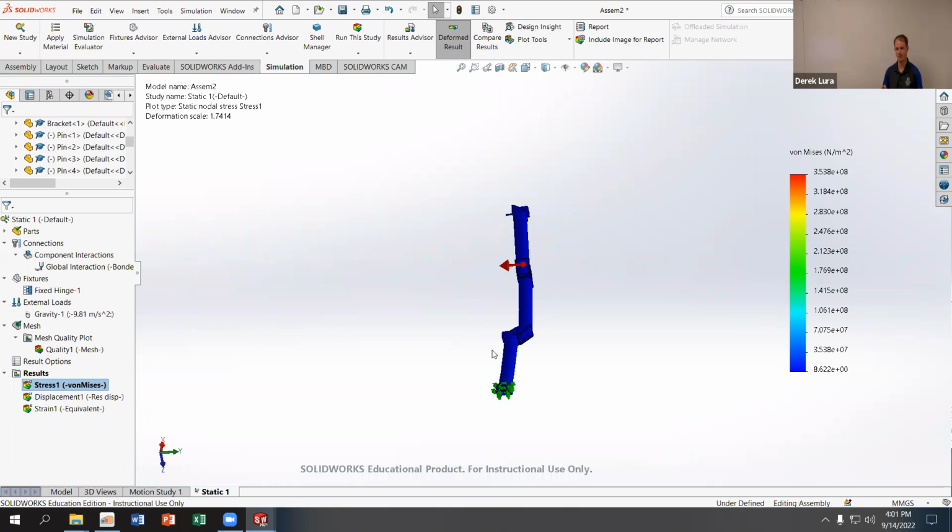The only thing that's going to be wrong with that is that if you have a beam that's curving like that, and I say you have a force of 100 newtons, as it curves, that distance is no longer what it originally was. It actually gets shorter. If you say no, this beam can go like this infinitely that way, like with infinite shear, because it's just going to assume that that 100 newtons carries forward forever. Or if you have large displacements, it'll calculate how that changes as it bends. And so you get a much more realistic deformation profile.